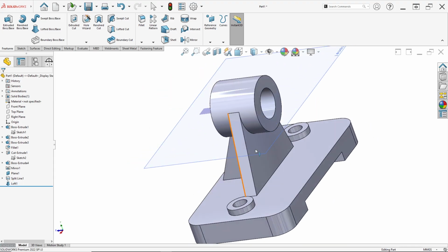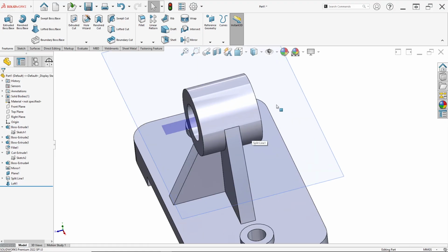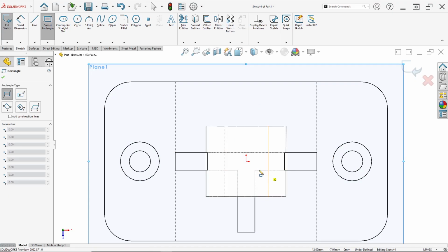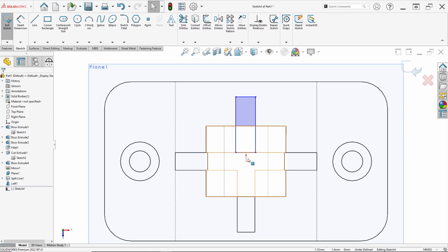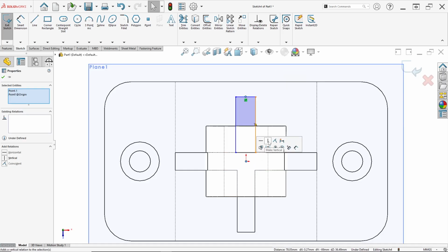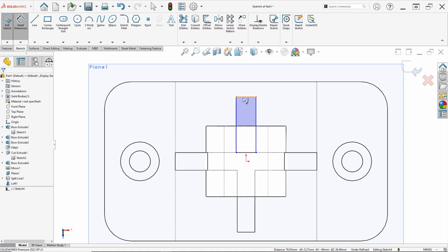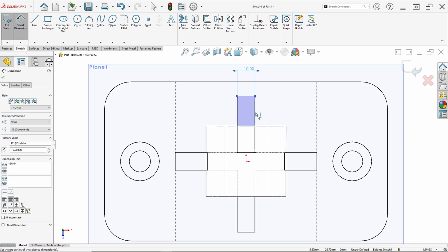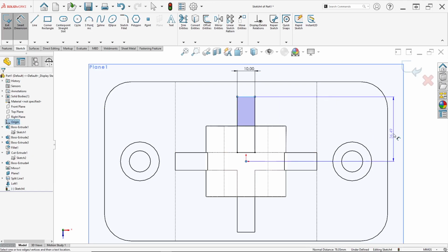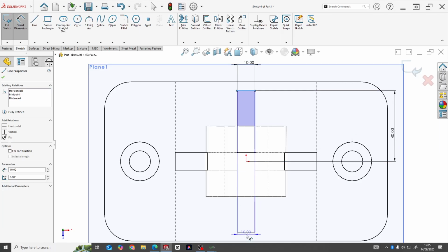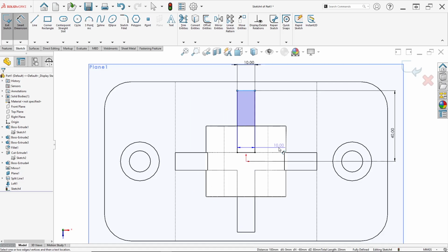So we can make another rib here in the same way. It's so simple. Right click on this face and click Sketch again. For display, click hidden line visible again and draw a corner rectangle like before. Ensure this point and this point, hold Ctrl on the keyboard and click make vertical. For thickness, use 10 millimeters, and for this edge to the center of the part, the distance is 40 millimeters. Automatically we can check this edge to this edge is 80 millimeters.